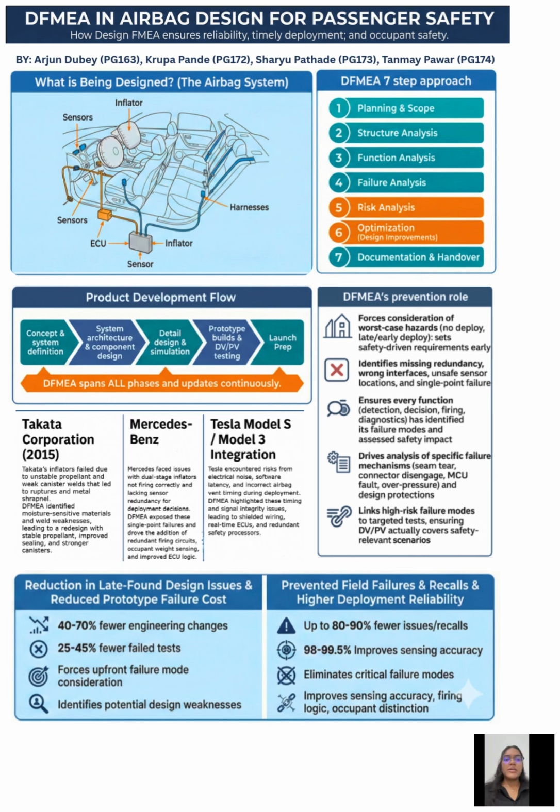Here, we break the airbag system into subsystems like sensor, inflator, cushion, and wiring to understand how they relate. Step 3 is functional analysis, where we identify what each part must do and detect the impact, like trigger inflation, maintain pressure, etc. Then step 4 is the failure analysis.